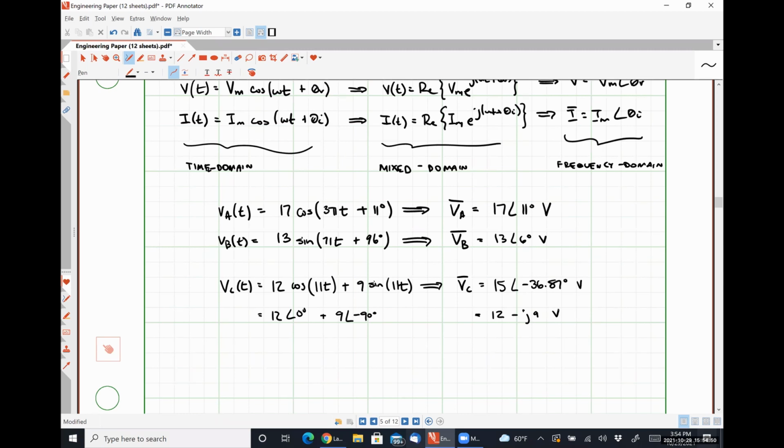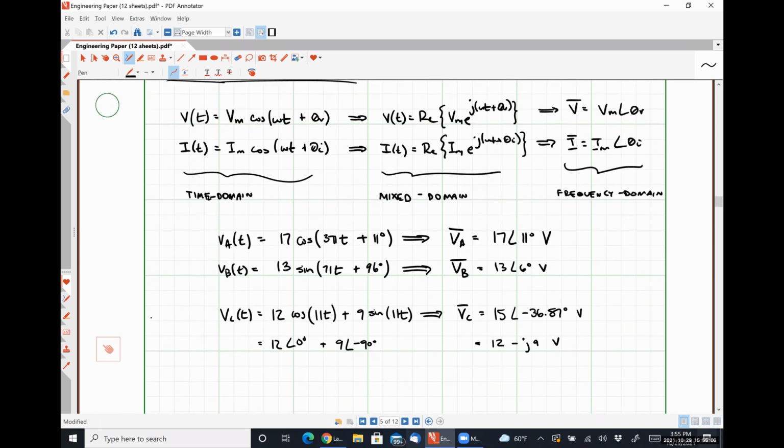Yes. So doing our conversion to polar using Euler's identity, we drop off the angular frequency. If you wanted to go backwards, there would be no way to know the frequency. So that is a fair point. This frequency domain representation does not carry that frequency term. You have no idea what omega is unless you are told. That is one of the downfalls of frequency domain analysis.